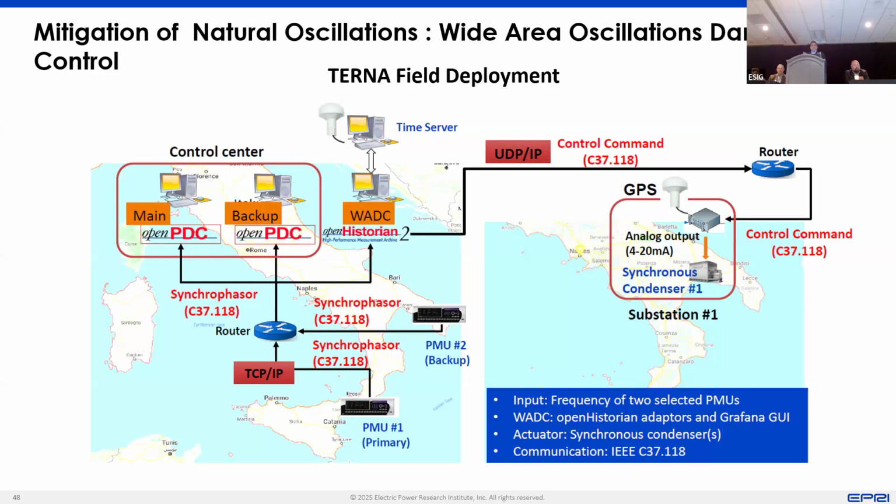So that's one of the ways, looking into other means of doing more autonomous wide area damping control, if your traditional systems like power system stabilizers are not available, or some of the machines where those power system stabilizers were installed have retired. So that's one thing we are looking into.